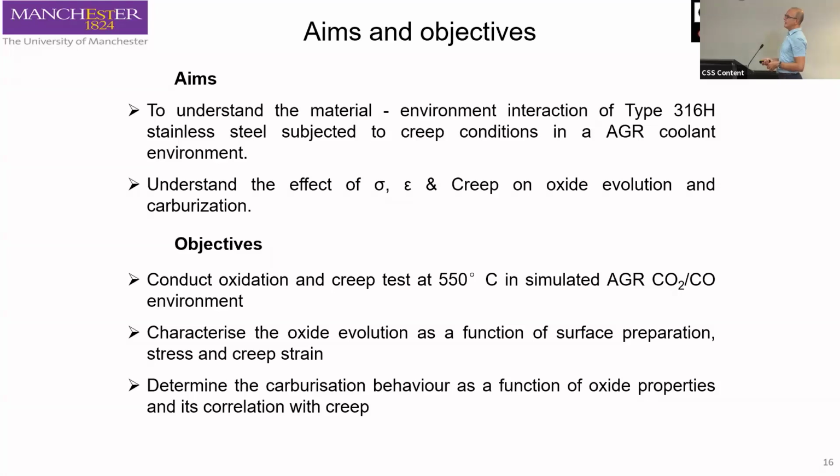We conducted creep tests in a simulated advanced gas-cooled reactor environment, and we wanted to identify also the effect of not only stress and strain, but also the effect of surface preparation and the consequences on the oxidation and carburization.